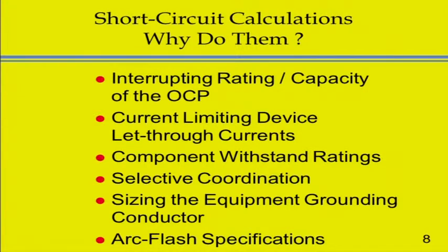Selective coordination is another thing that has to be considered, and that is when you have a fault, you want the device closest to the fault to open. That doesn't always happen. It has to be taken into account doing the design of the system to be able to set the overcurrent devices so they trip appropriately so that only that device closest to the system will shut down.